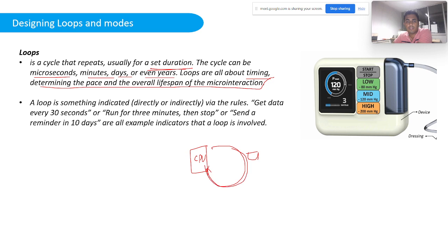You'll be looping continuously to read that sensor data every 3 seconds, and then you will be controlling, this is the third second, every fourth second you change the current of the particular motor. Again, in the fifth, sixth, seventh second, you again measure the sensor value, and again you run this particular motor. So this is what loops are.